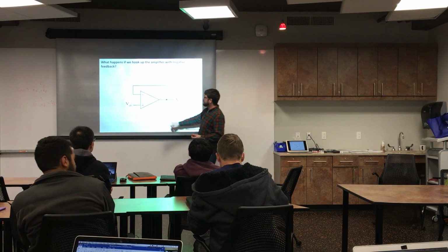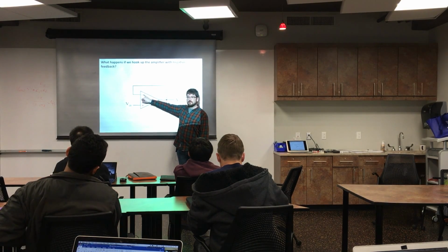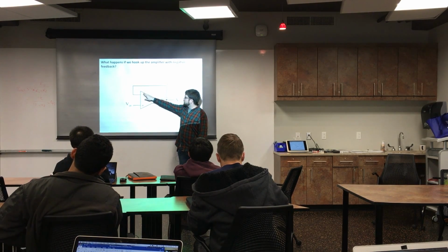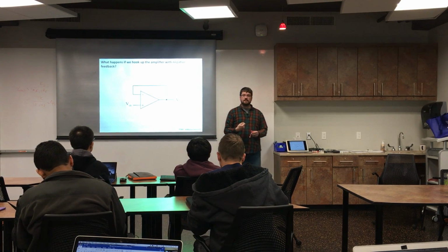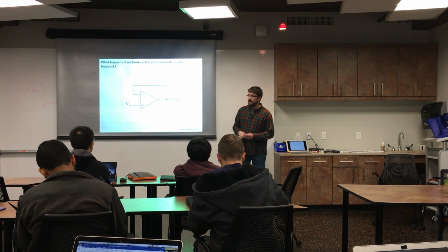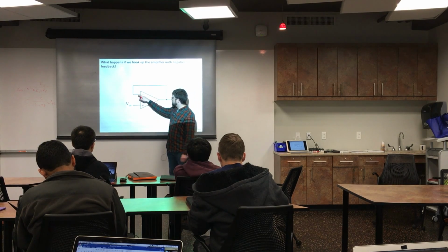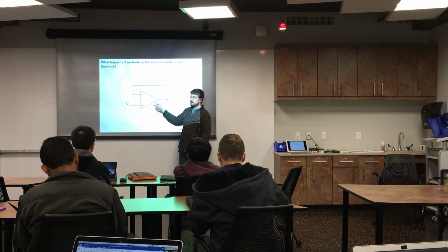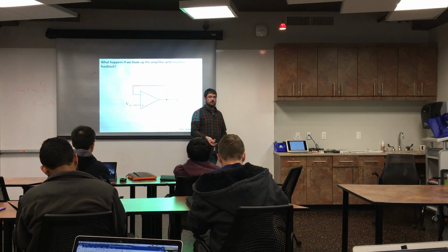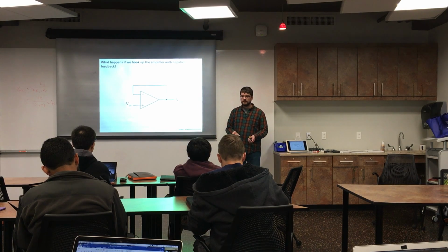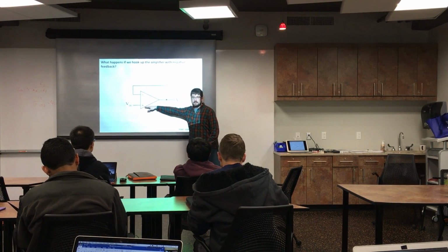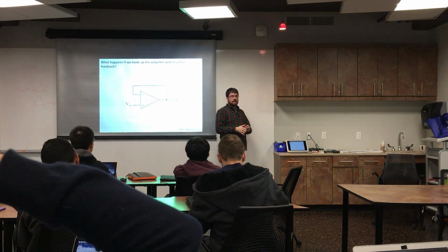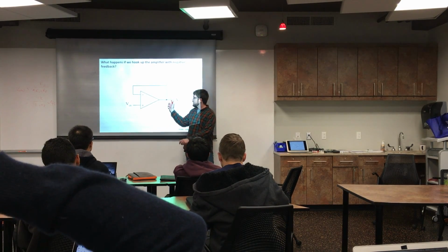So now the difference between these is getting smaller and smaller and smaller. The voltage here is rising towards 1 volt. That means that the op amp starts backing off on its output. And eventually, there's 1 volt here. So the difference between these is 0, what the op amp ideally wants. So that creates a voltage follower. The output here does whatever happens here. We talk about the op amp kind of hunting for the voltage.